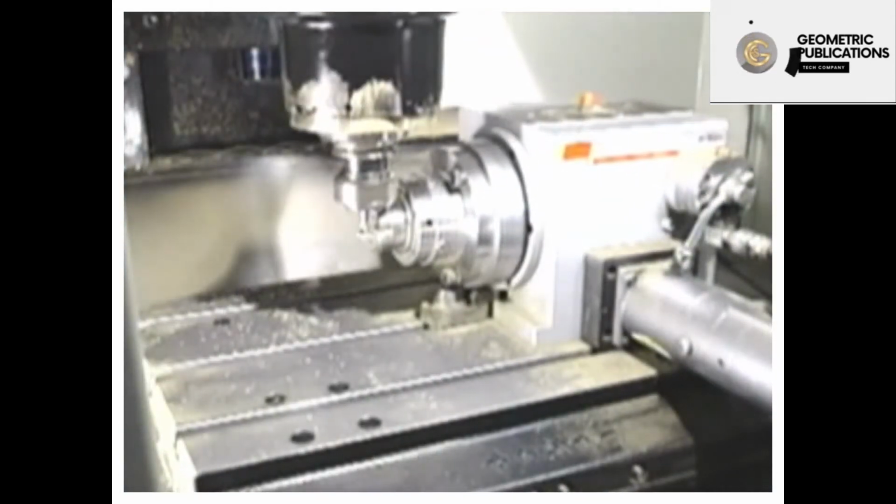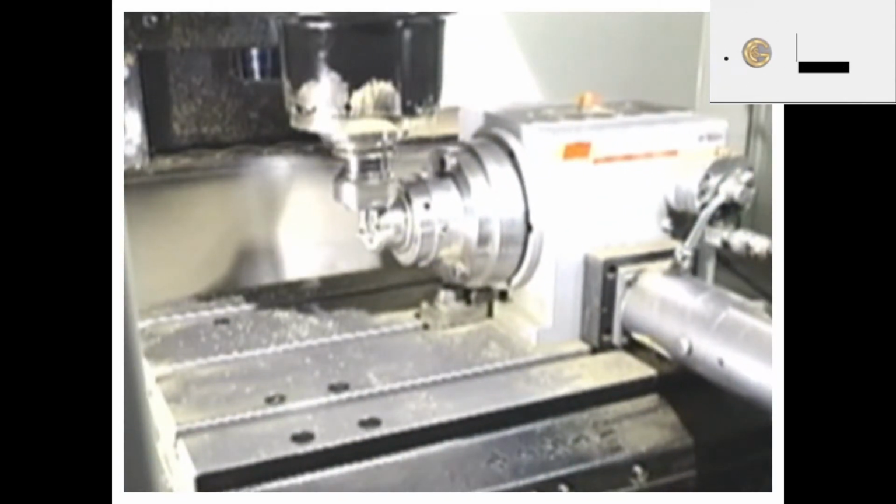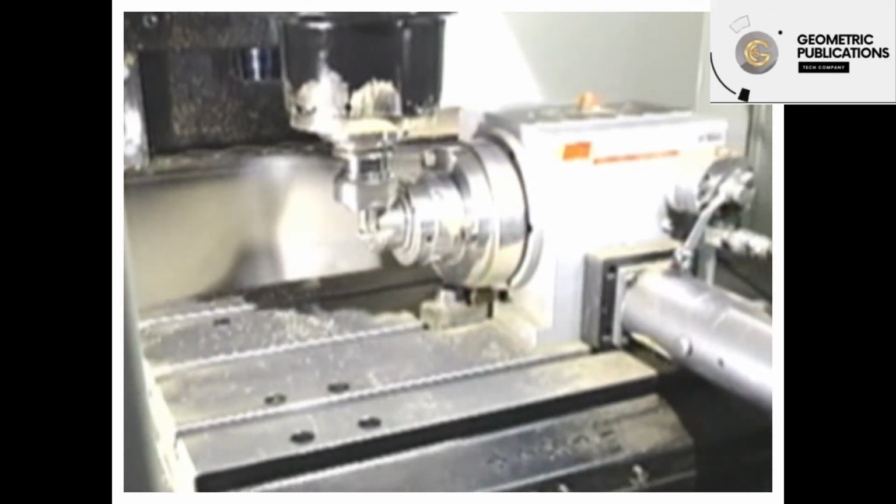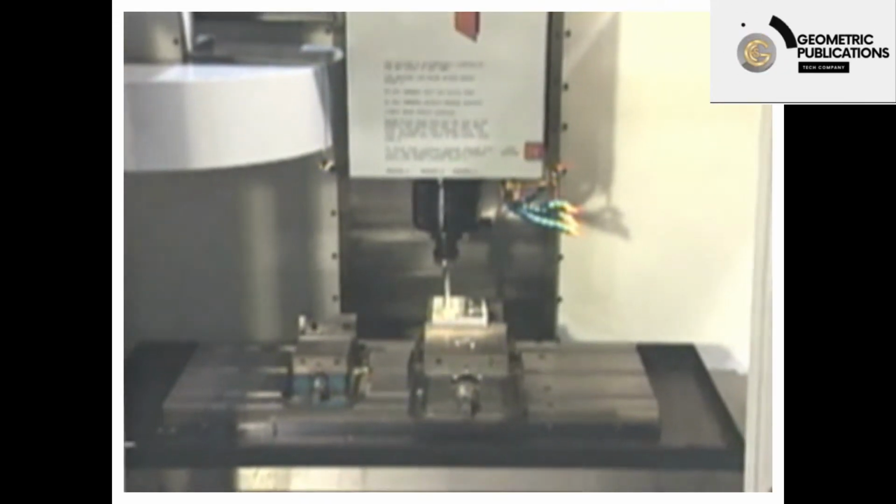If a rotary table is added on the machine table, then there is a 4th rotary axis, which is called the a-axis. The method of accurate positioning along each axis for all machine types is achieved using the rectangular coordinate system. On the vertical milling machining center, the horizontal baseline of the rectangular coordinate system represents the x-axis, and the vertical baseline represents the y-axis. The z-axis is at a right angle perpendicular to both the x and y axes.